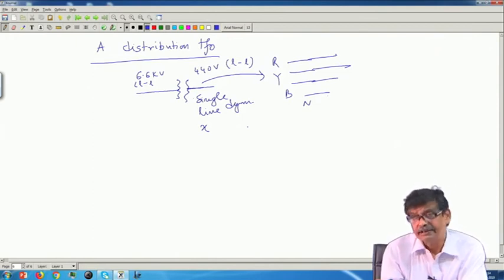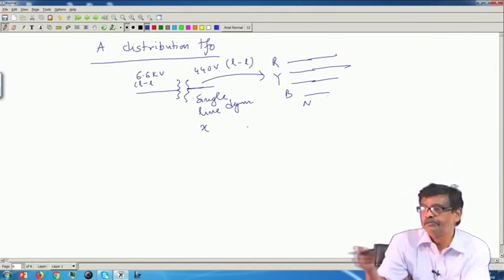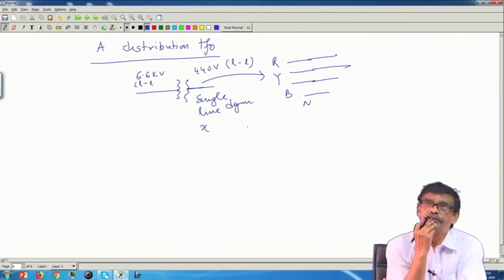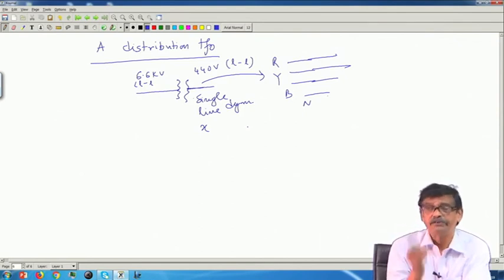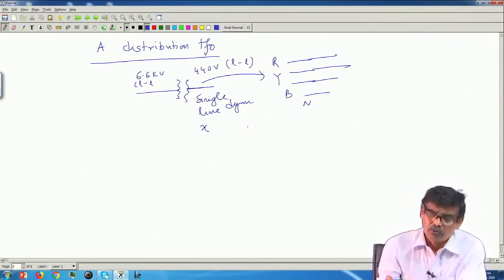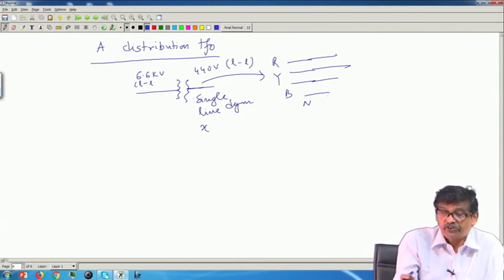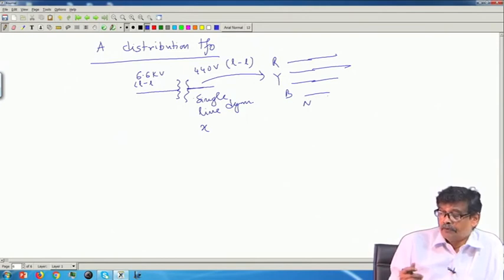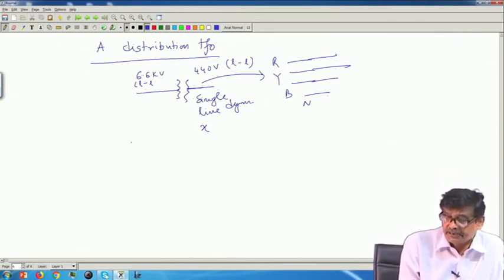But here is another extreme example, where a distribution transformer secondary supplies different consumers and the degree of loading on the transformer goes on changing and goes on changing wildly. You do not know, but your primary is to be energized. Now, to qualify, therefore, another efficiency is calculated for such a transformer, where load fluctuates over 24 hours with primary energized continuously, and that efficiency is called